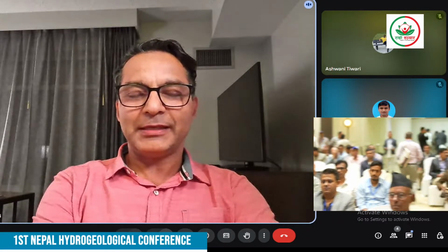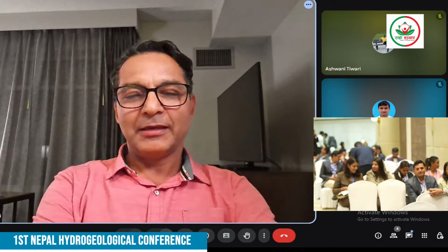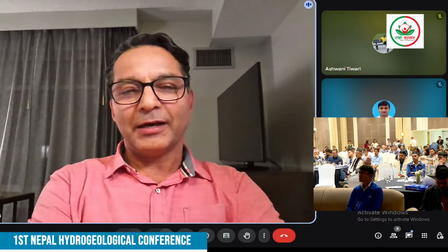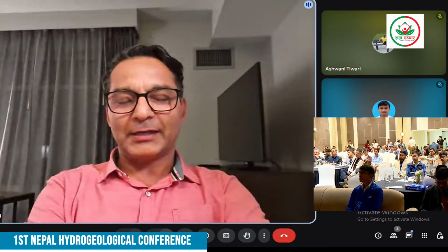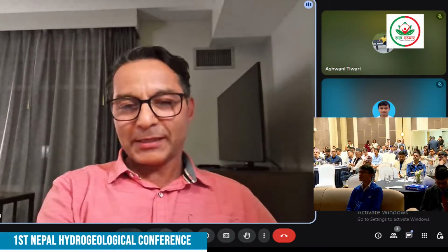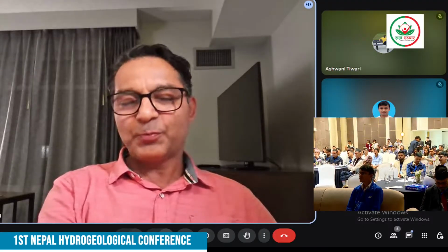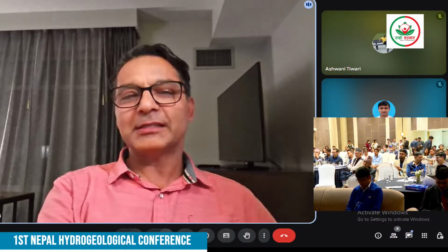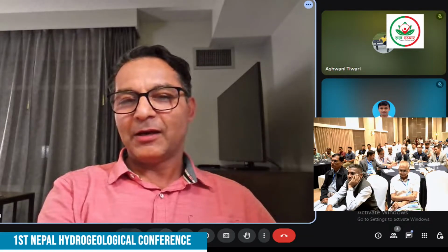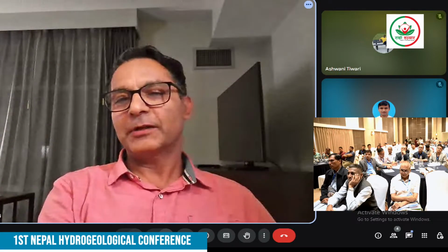What this means is if the redox chemistry drives iron reduction, making iron 3 to iron 2, then whether it's phosphorus or arsenic, that releases out of the aquifer. So I think just measuring the redox chemistry of iron could provide you a very good insight into the leaching potential of arsenic in an aquifer.